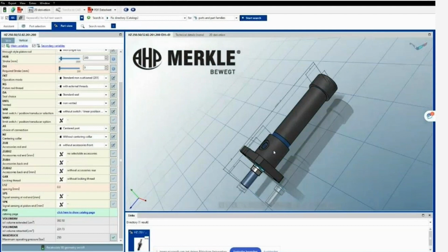Okay, so both of them can be used both in die casting and in plastic mold making. For example, we at AHP do something that many other producers don't do. Our piston rod, it's always hardened. Many producers don't have it hardened, it's only chromed. But we do this so we can cover the whole scope of die casting and plastic.